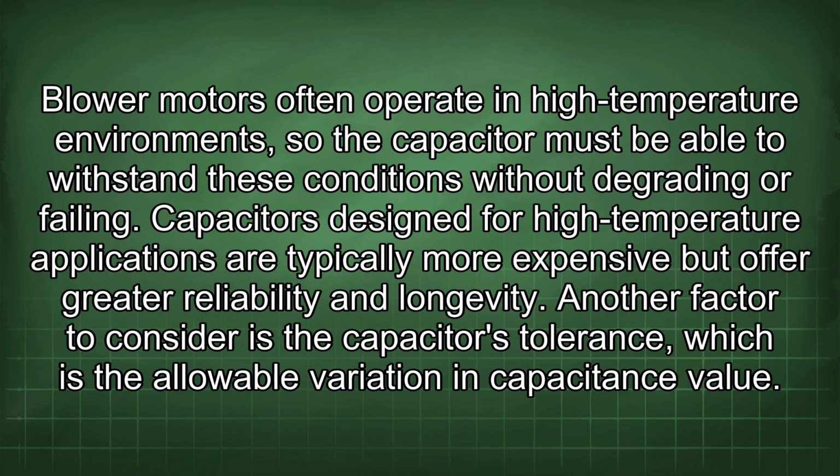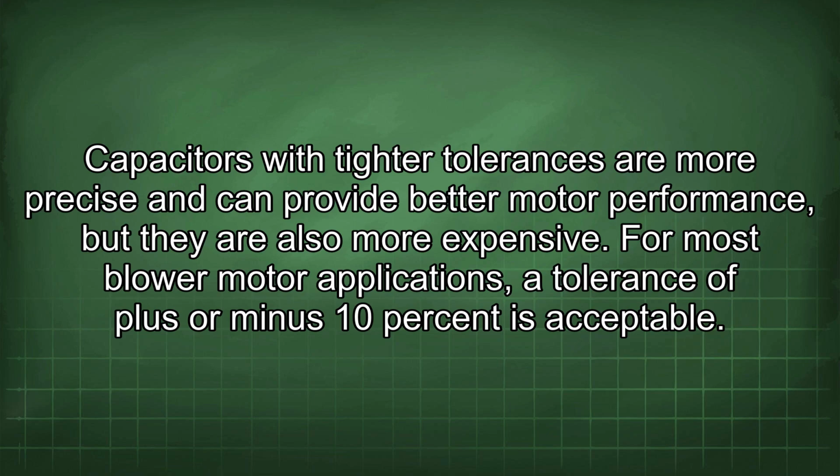Another factor to consider is the capacitor's tolerance, which is the allowable variation in capacitance value. Capacitors with tighter tolerances are more precise and can provide better motor performance, but they are also more expensive. For most blower motor applications, a tolerance of plus or minus 10% is acceptable.